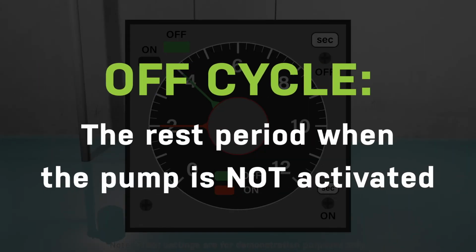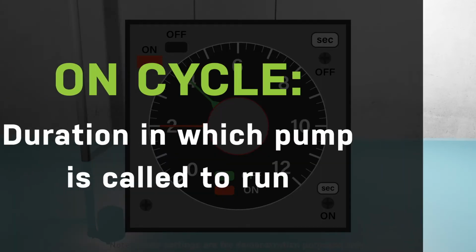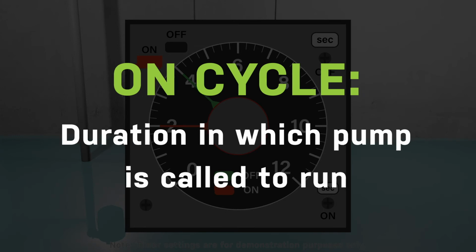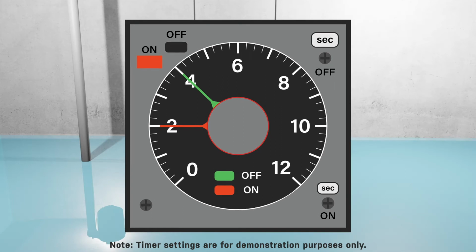The off cycle is the rest period in which the pump is not activated. It is the minimum amount of time between the on cycles. Once the off cycle has concluded, the on cycle will commence. The on cycle is the duration in which the pump is called to run. If the timer enable low level cutoff float is still lifted up after a completed on cycle, the panel will call for another dosing sequence, starting with the off cycle.